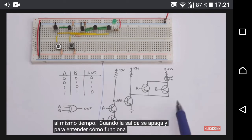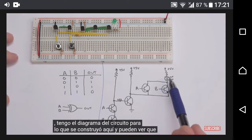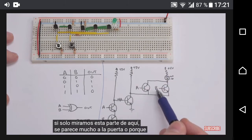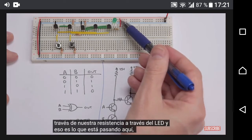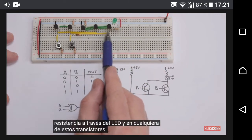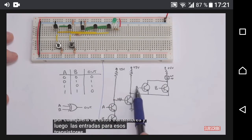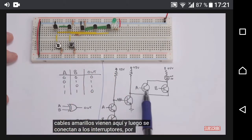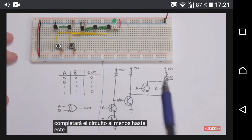And to understand how that works, I've got the circuit diagram for what's built here. And you can see that if we just look at this part over here, it looks a lot like the OR gate, because we've got the 5-volt source going through a resistor, through the LED, and into either of these transistors. So it can go through either of these transistors. And then the inputs for those transistors are the A and B. So these yellow wires come over here and then jump over to the switches. So if either this or this is on, then that'll complete the circuit at least through to this point.